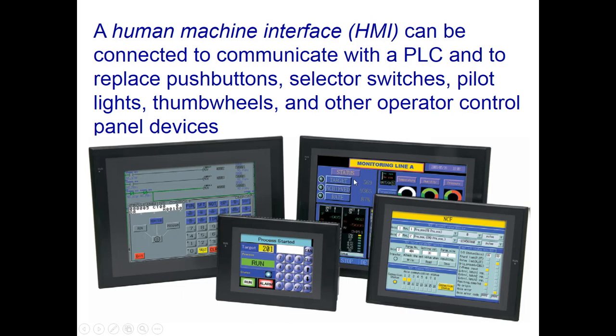Okay, so the HMI is a way to push data, whether it's Boolean or registers or something like that, into the PLC, and it's also a way to read the status of those items while the PLC is running.